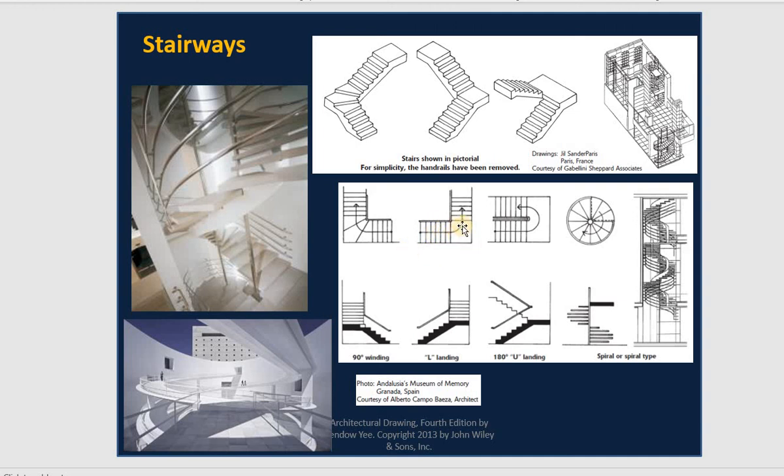So we have many stairs, and after that we have the landing. This one cannot be smaller than 3 to 4 feet wide, and to go up to another level like this, the landing is usually 4 to 5 feet, and you call that the U shape, and the landing is double like this. And this one is the handrail and the guardrail, and this is the step.